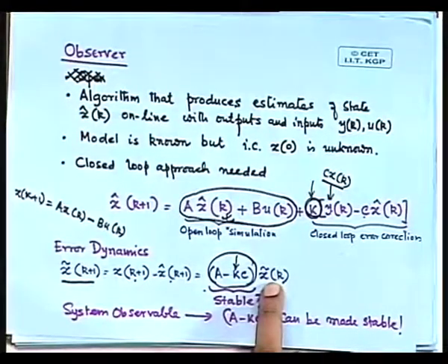What will stop you actually is what we have not considered. We have not considered any measurement noise. But if you have measurement noise and if you make this k high, then all that measurement noise will actually come into your estimates. Theoretically you will get a very good estimate if you make k such that the poles are deep in the left half plane.